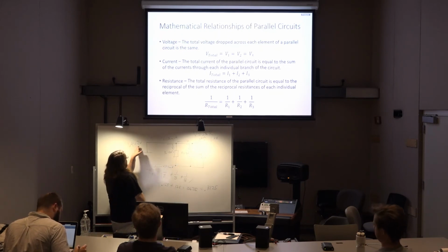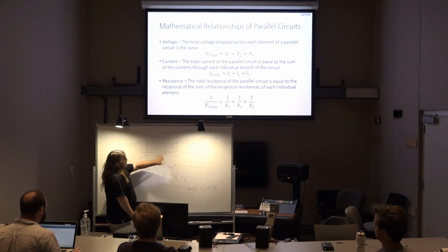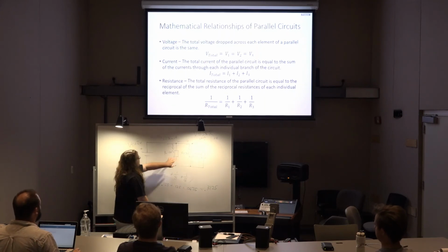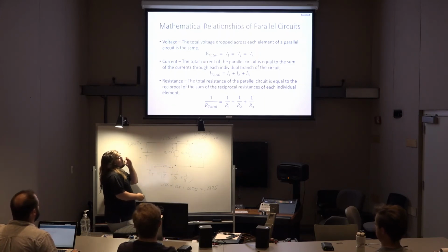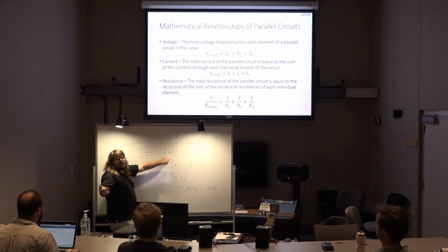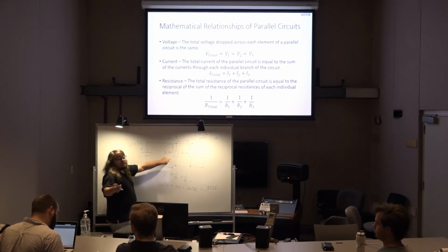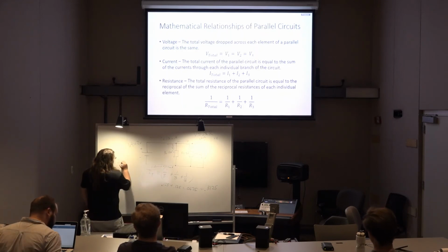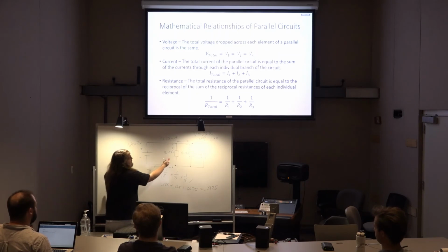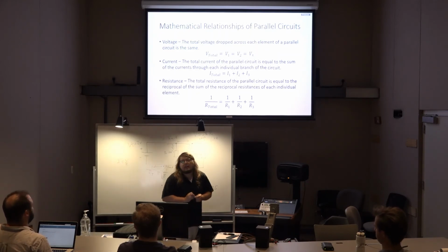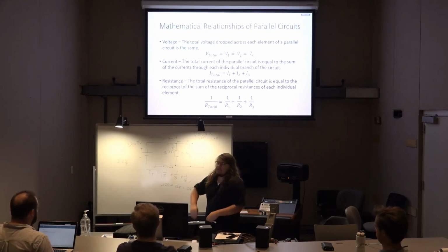So we know that there's 2 volts across each lumped element. We know their individual resistances. Based on that and Ohm's law, we could figure out the current through the circuit, right? We did it earlier. I equals what? V over R, right? So I equals V over R. You'd simply go through for each element in the circuit and grab all of those individually.